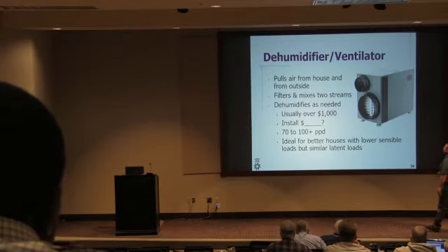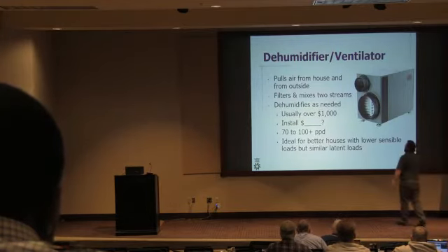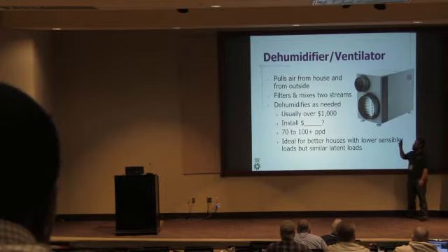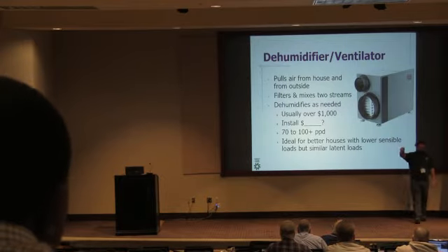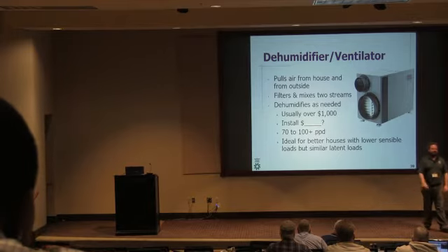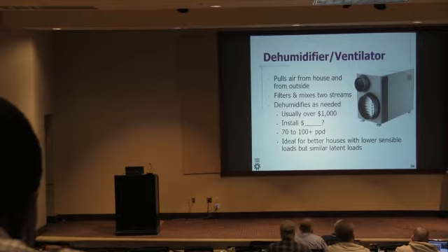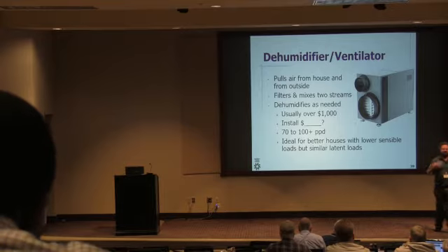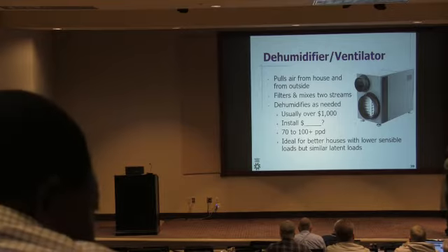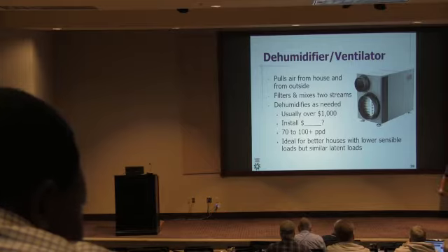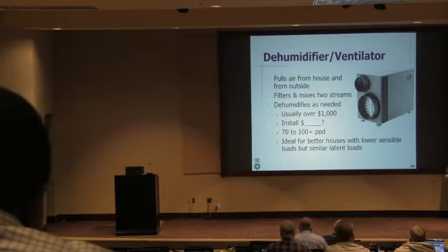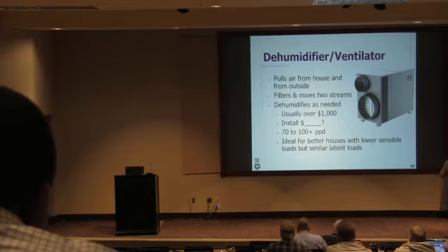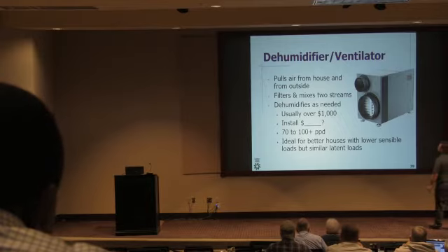Here's another one, and I will say we had the manufacturer of one of these products come Tuesday to speak to our state codes council. They've gotten the prices down on these things to more like the $500 price range, and these are the best option for our climate. They're a dehumidifier ventilator. So it's going to provide ventilation air. It's also going to dehumidify that incoming airstream. And what do we say? It ain't the heat, it's the humidity. The humidity is the comfort factor that we really care about.